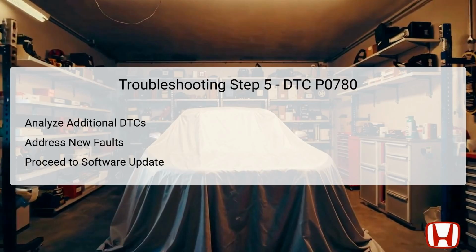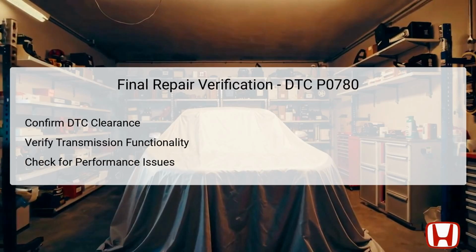of the troubleshooting process. After completing the troubleshooting process for DTC P0780, the technician must verify the repairs made to confirm that the issues have been fully resolved. This includes checking that the DTC has been successfully cleared from the vehicle's memory after repairs.